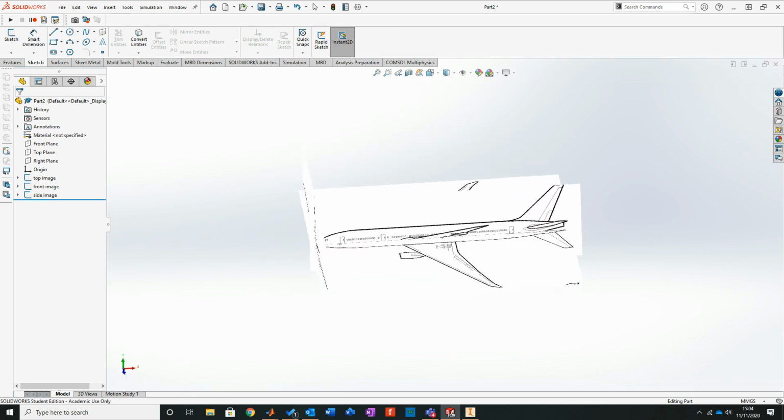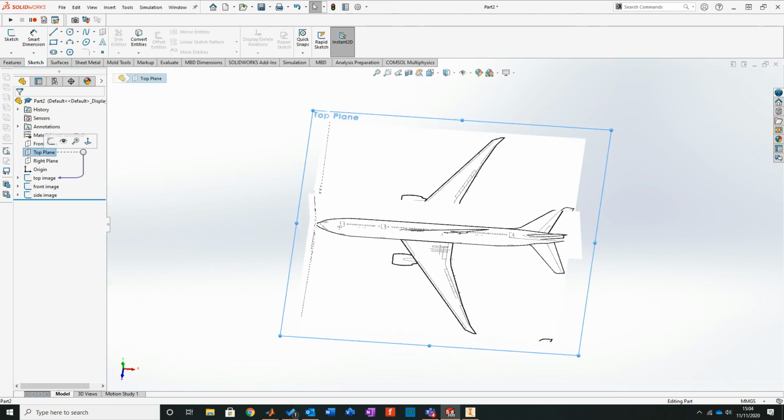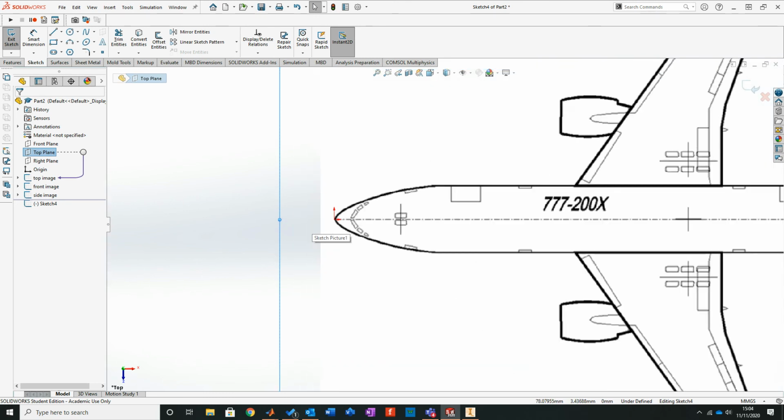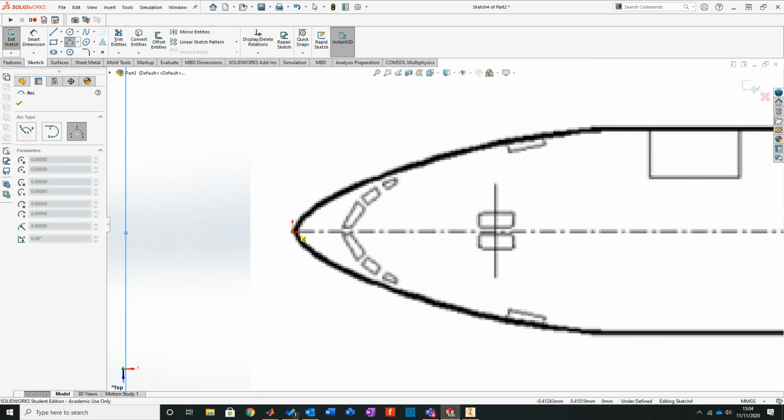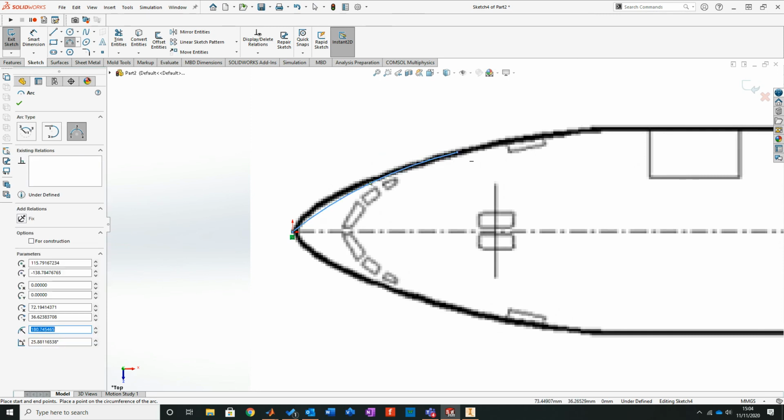With this now, I can start to look at generating this a little bit more. So if I click there, Control and 8, zoom that right in there, and you see there, it looks like a 3-point arc. Arguably, it could be a 3-point arc, but if you look again, it's a 3-point arc, then a secondary 3-point arc with a tangential relationship. Use that as my datum marker for the start, bring that in, and then bring that to there.